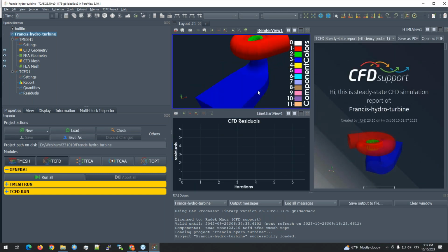This geometry consists of 3 components. I won't go into much detail, but we always build the geometry from components, which are parts that have some kind of internal meaning for the whole machine. Typically, we have parts which include volutes, sometimes also the vane gates or the guide vanes, or we have a component just for the rotor part and for the draft tube part.